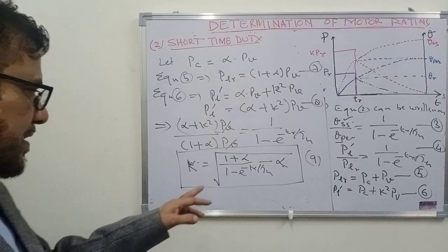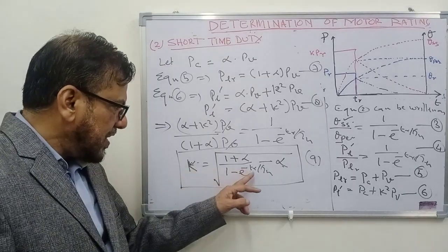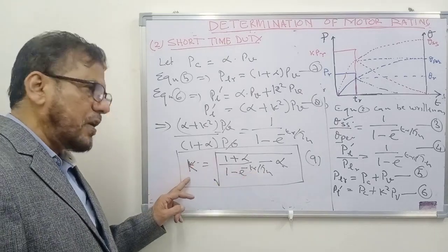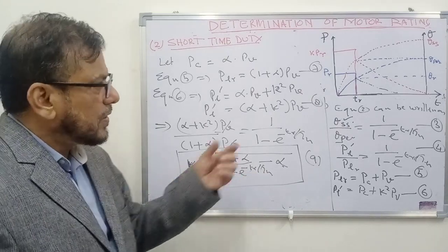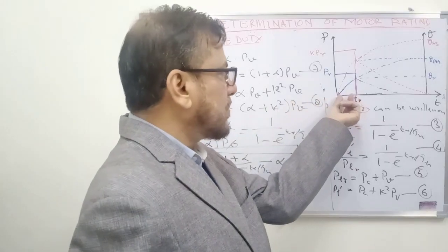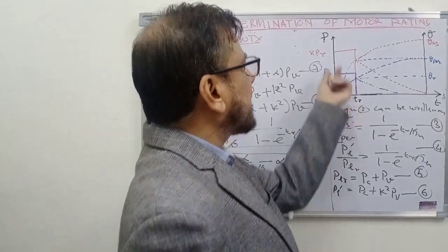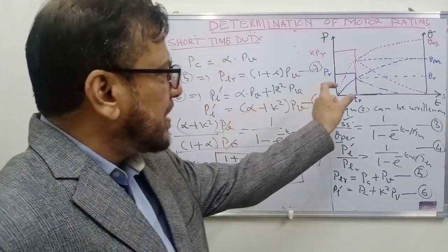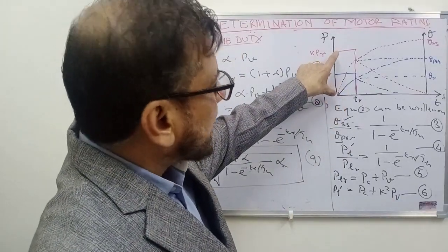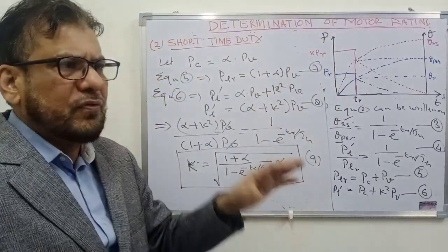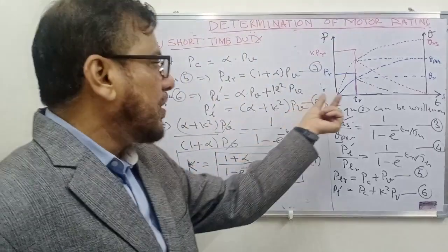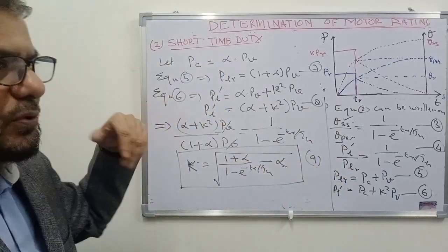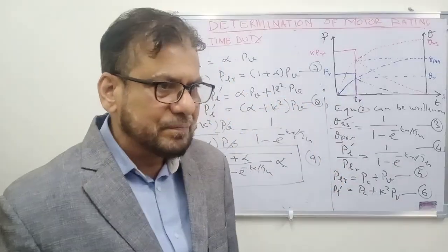So this means that the lesser the value of tr, the higher the value of k. So the lesser the time for which the motor is loaded, the higher you can overload the motor. So if the loading period is very small, the factor of k may come as 3, 4, 5, 6 depending on how small the loading period is. But you cannot overload the motor indefinitely.